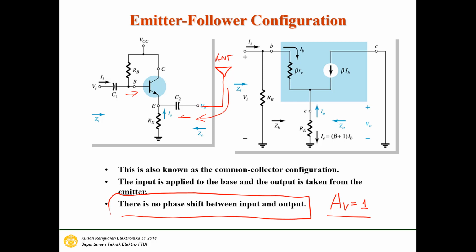And then another function of the buffer is output impedance matching. So if we have a system here, this is another amplifier, and that amplifier maybe has a high output impedance. We would like to match it with the antenna. Antenna typically has 50 ohm or 75 ohm.